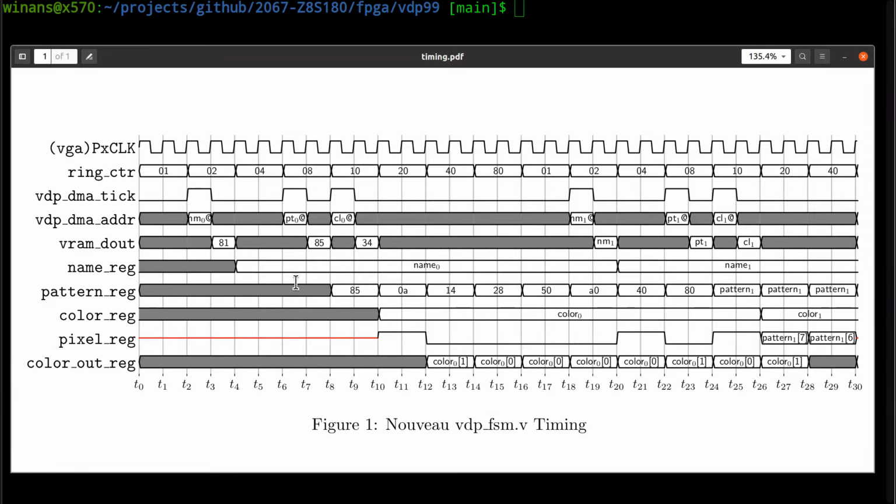So there's this notion of jumping back and forth, and I talked about that last time when we went over the VRAM stuff. This is this other control signal that reaches in and says, I want this, I want it right now. So in the very next tick, if DMA tick goes on, that's the state machine saying, I need to know the byte value at the address right here, and I expect to get it on the very next clock. Bam, okay? That's what this is doing.